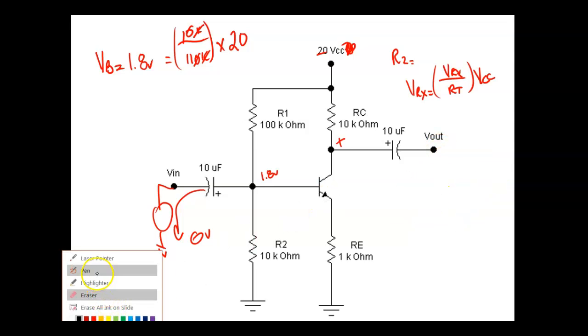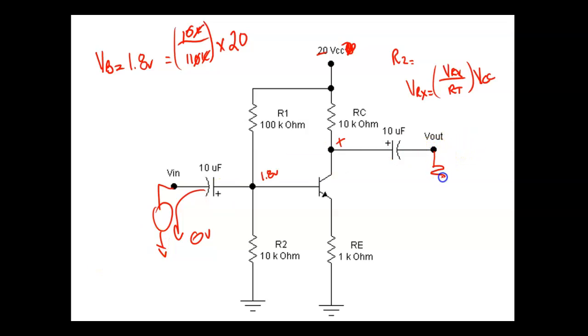Eventually, guys, we're going to have to come up here and hook this up to some type of load. It's going to be considered a resistive load even if it's another amplifier. Normally, when we amplify, we go through stages. Right now, the maximum voltage I could bring into this would be probably 1 volt peak-to-peak, because if I ever get down below 0.7 of a volt, the transistor's going to cut off, and we'll clip the top.